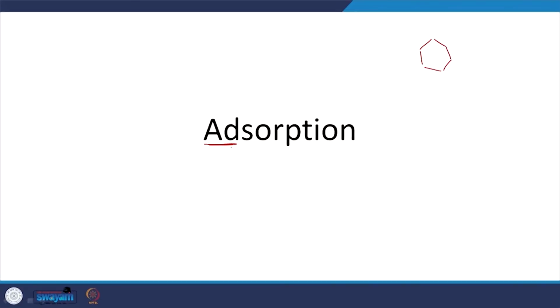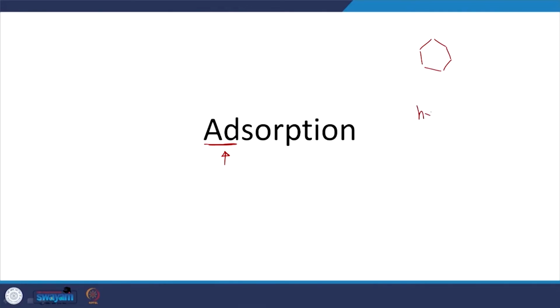So, here we are going to use a different principle. The principle is that I am going to have a media, right, and this will be able to adsorb. The key aspect is AD, adsorb. We will come back to look at what this is, adsorb, right. It will be able to adsorb this organic matter, or that organic matter which is hydrophobic. So, we are looking at a couple of terms here. One is adsorption, and the kind of compounds we are trying to remove are typically hydrophobic.